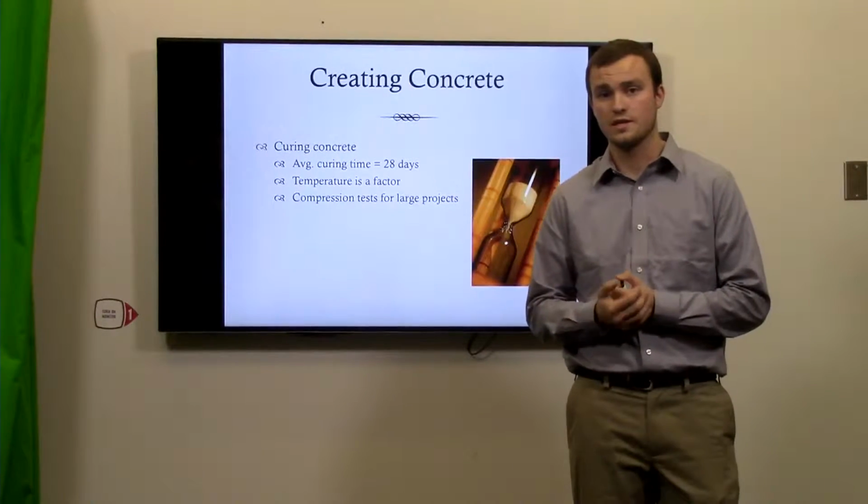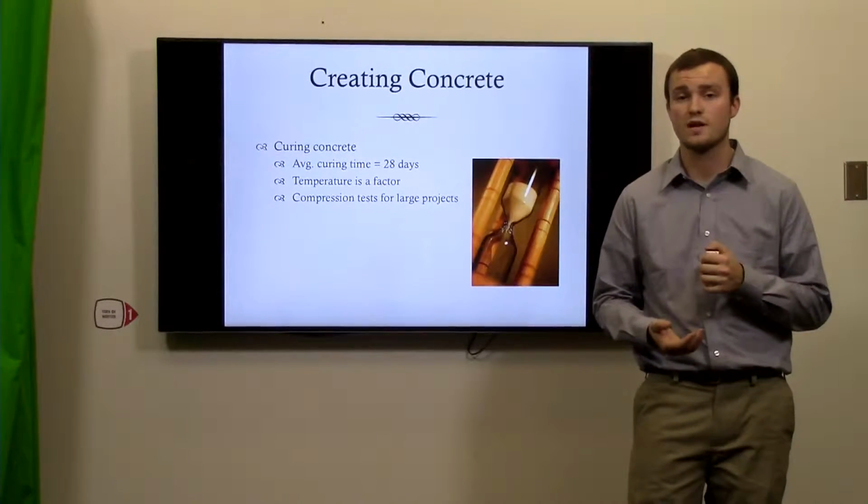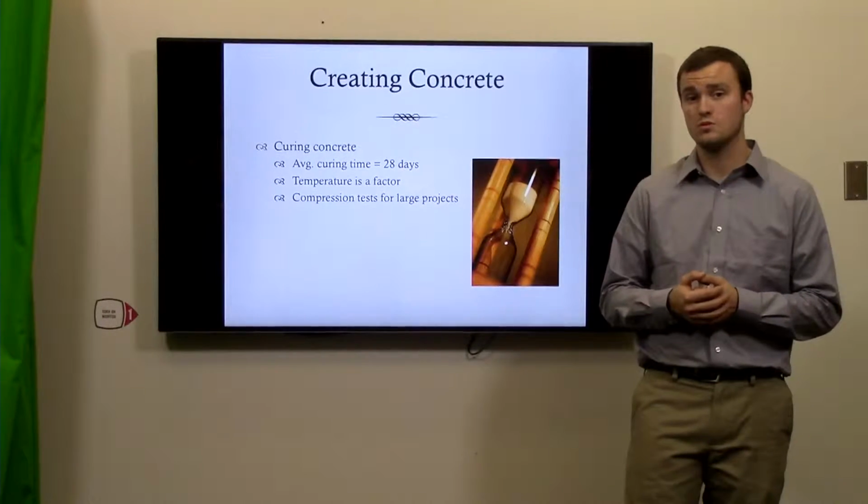Let's say that you're doing a project in December. You're going to need to use something like heating blankets over the concrete to ensure that the strength isn't compromised due to the cold weather.